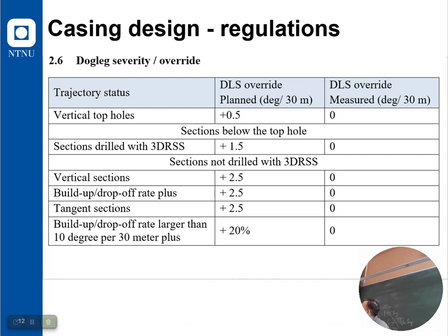And it's the same for more deviated ones, and you add curvature to any calculation that you do, it increases the bending stress, if you see what I mean. It gives you an addition. You need that because the casing would not be straight, and even if you underestimated the dogleg, you have something to go on here. Yeah.